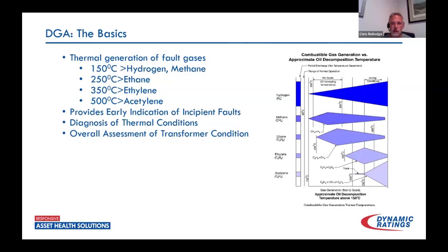And of course, the greater that thermal variant goes up, the more damage that's being caused. So once we get up into this 700-degree range, yes, we're totally wiping that solid insulation, which is also affecting clamping strength, exposing us to a quicker failure through faults. But just with this small bit of knowledge, we're able to take a quick look at a DGA sample and understand, okay, what kind of internal temperature with this defect are we seeing?